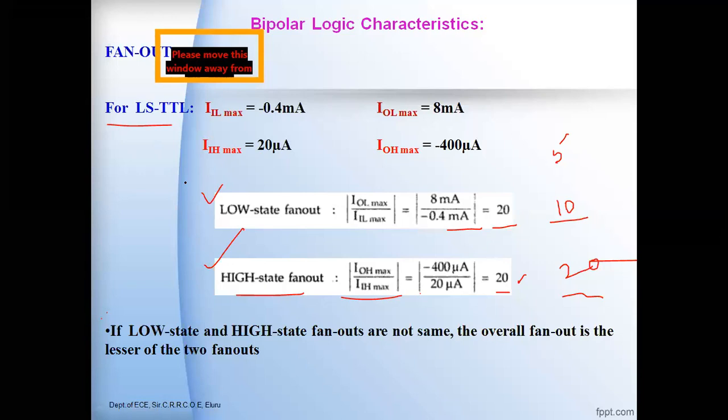So it results in increasing the transition times. It increases the propagation delay, which results in decreasing the speed, and the voltage parameter values will also change. Once the voltages change, the circuit will not function properly. Therefore the fan out is one of the desirable characteristics. Knowing the DC value, we can connect the maximum gate inputs to a single gate output. The same is the case for fan in also.